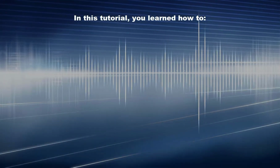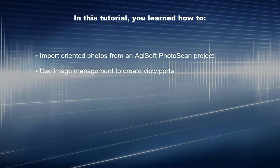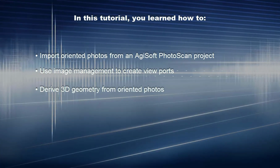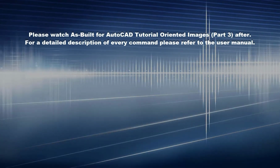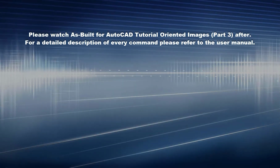In this tutorial, you learned how to import oriented photos from an AgiSoft PhotoScan project, use image management to create viewports, and derive 3D geometry from oriented photos. Please watch As Built for AutoCAD Tutorial Oriented Images Part 3 Next. For a detailed description of every command, please refer to the user manual.